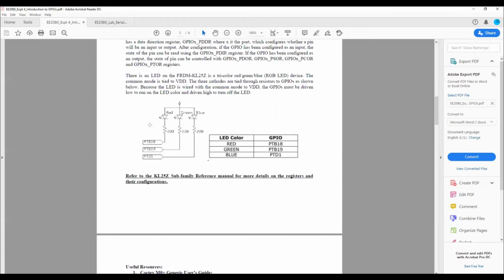And then of course, this is something like negative logic, right? If a 0 value comes here, that means this is already connected to plus 3.3 volt, and then it gets connected to the ground if 0 comes here, and then current flows through this LED and it glows up. So if you write 0 to this pin, this glows up. If you write 1 to this pin, it switches off. So that is very important. It's negative logic. Please remember that.